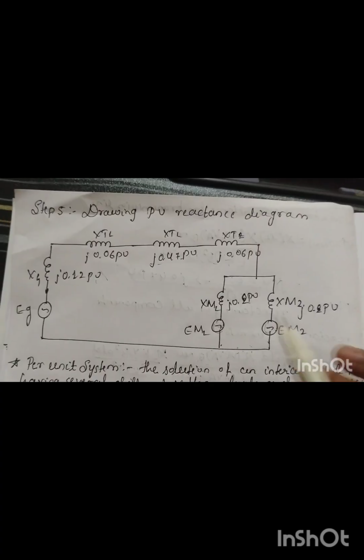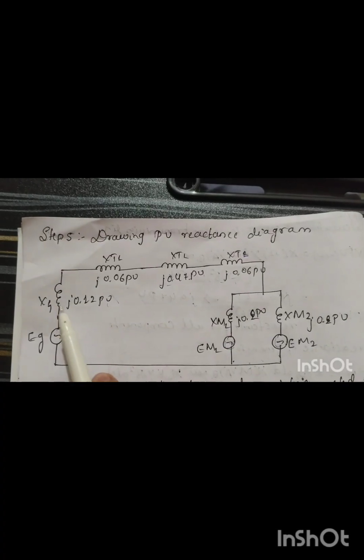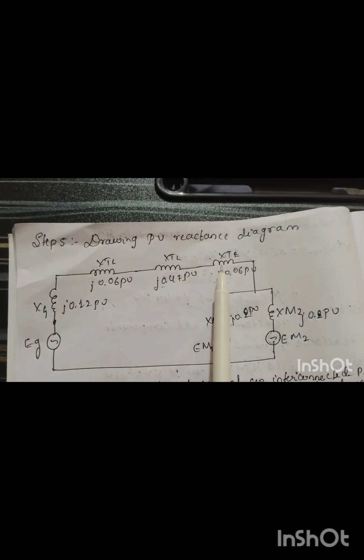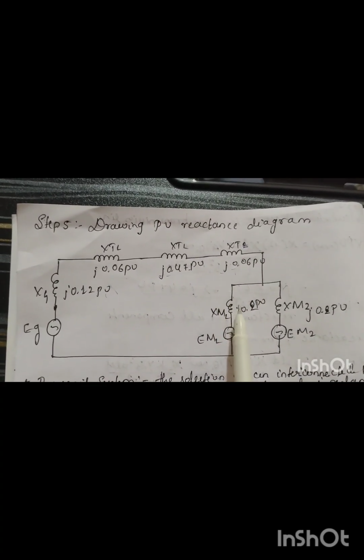Okay. In step 5, we need to draw the per unit reactance diagram. One generator is there, no? We need to draw one reactance along with the source voltage. And for transformer 1, we need to draw the reactance. Transmission line, again one reactance. For transformer 2, again one reactance. And two motors are connected in parallel, right? So, this is one reactance along with the source voltage, and one reactance along with the source voltage. This is called XM1, this is called XM2.